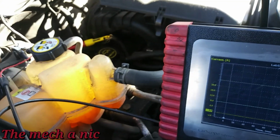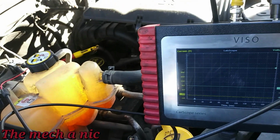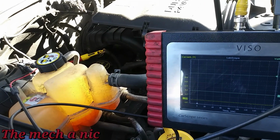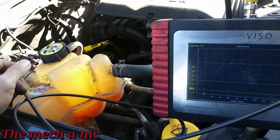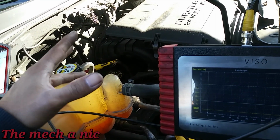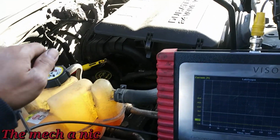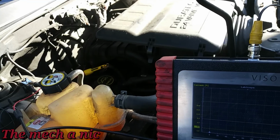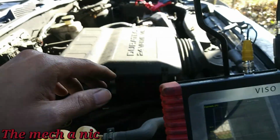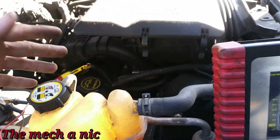Okay, so I went ahead and shut off the engine so it's easier for you guys to hear me. But it's been running for about 30 minutes and I can't get it to act up. It's been running perfectly fine, no misfires, no anything. I tried to put load on the engine to get the engine to rock back and forth a little bit. I tried wiggling the wire harness and nothing. I just wanted to get set up here. Okay, so we got our current clamp going for the current ramp, and I'm tapped into fuel injector number 4,